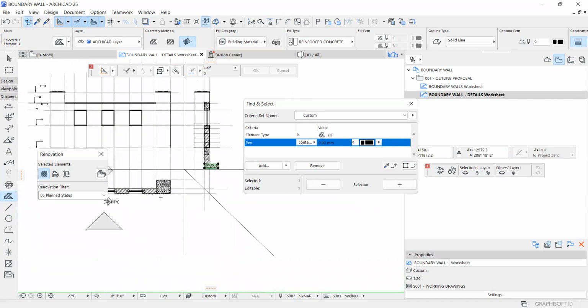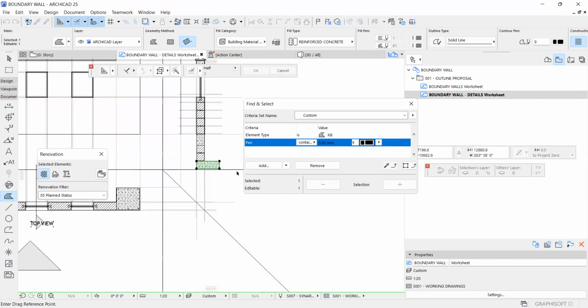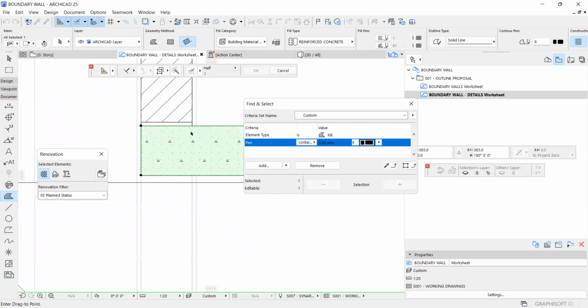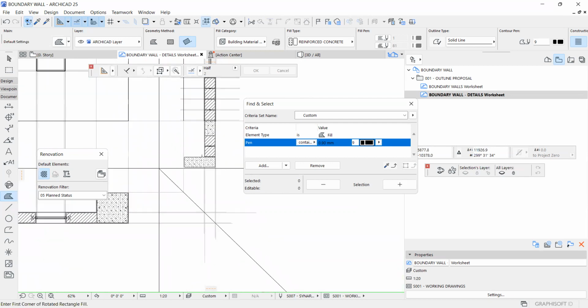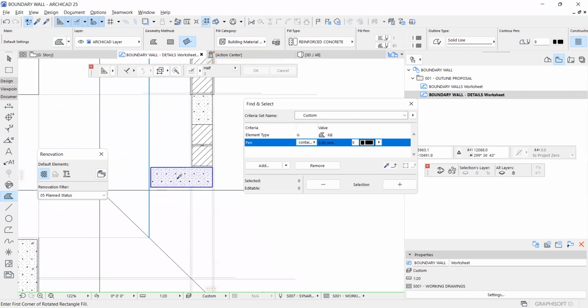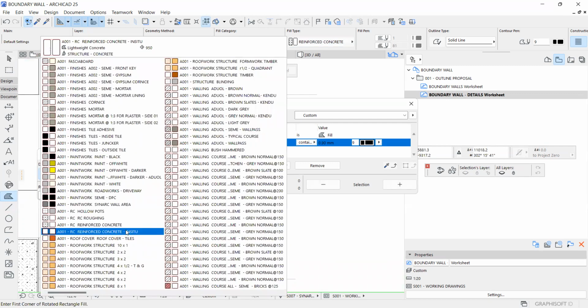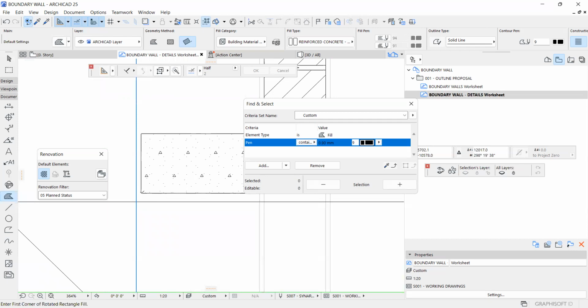In our case, it's on this side. You have to respect your neighbor, okay? It's on our side, okay? And then below it, usually have, call it a blinding. It's the non-structural concrete. For us, we'll use 50. Split again.